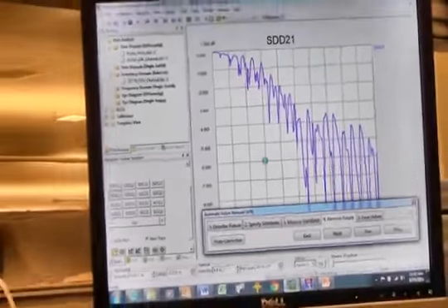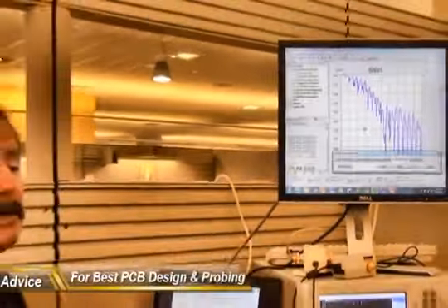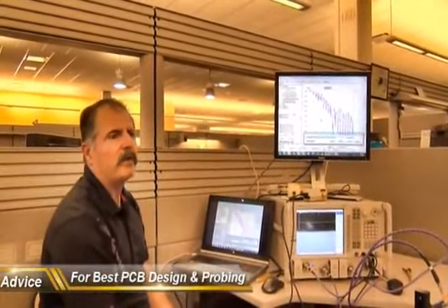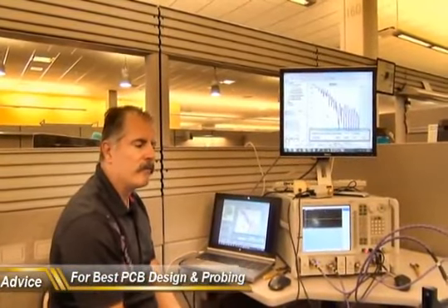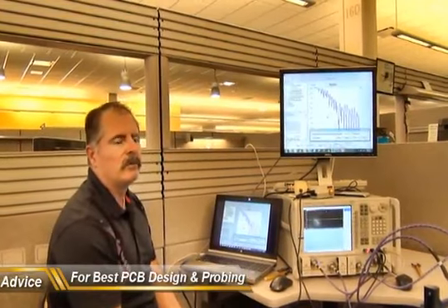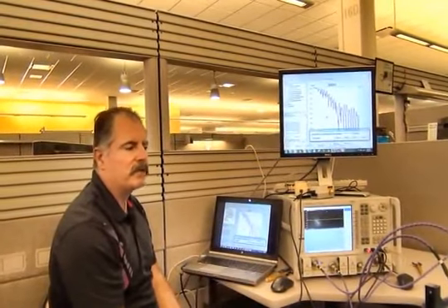You don't want to make the mistake of thinking, well, I'm going to de-embed the probes anyway, so it really doesn't matter how good the probes are. That doesn't really hold at all. You want to get the best PCB material, you want to get the best probes, you want to be able to really get the best quality of signal integrity measurement before any of this error correction happens.